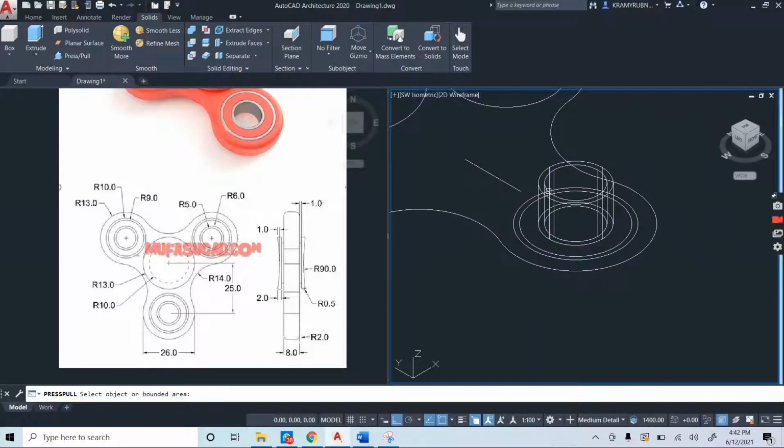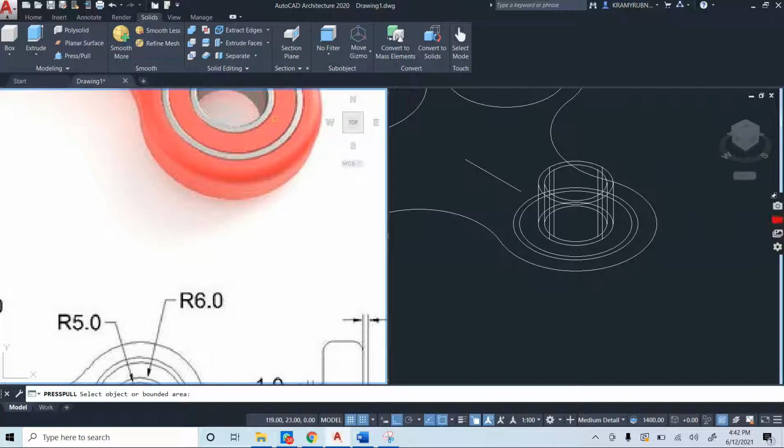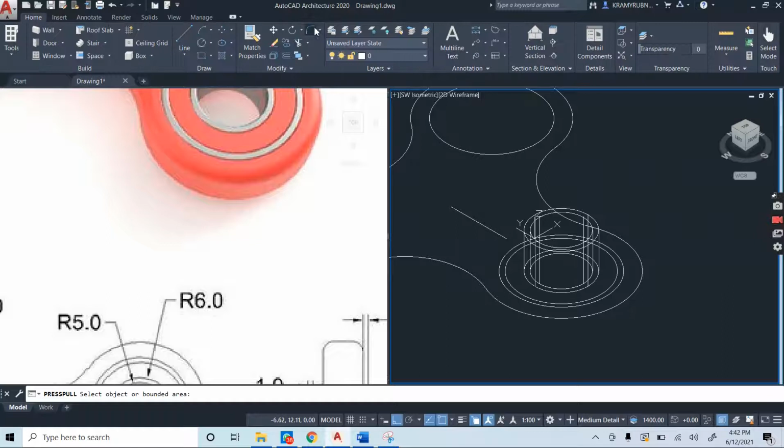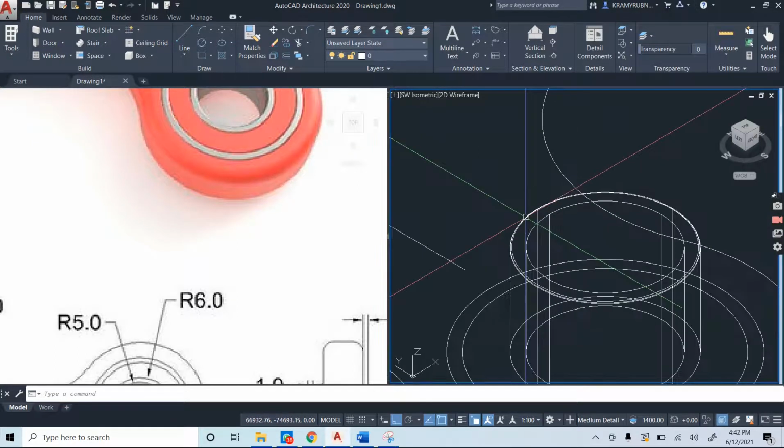Enter. Now one other thing to notice is that, to show separation between the pieces, I'm going to be giving the edges a slight fillet. I'm going to give a fillet of radius, and it's going to be a small fillet, let us say 0.1, enter, just so as to give curvature to the edge of our silver piece. Let's do it to the inner edge as well.